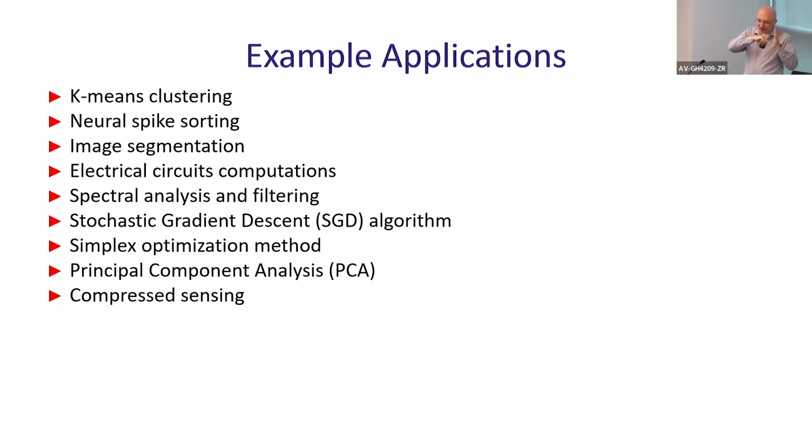But if it is a very slow signal, without fast ripples of some kind, then you can reconstruct it exactly using sinc functions. It's like sine x divided by x functions. These are base functions with which you can reconstruct exactly the original continuous signal from points. So you have that condition.